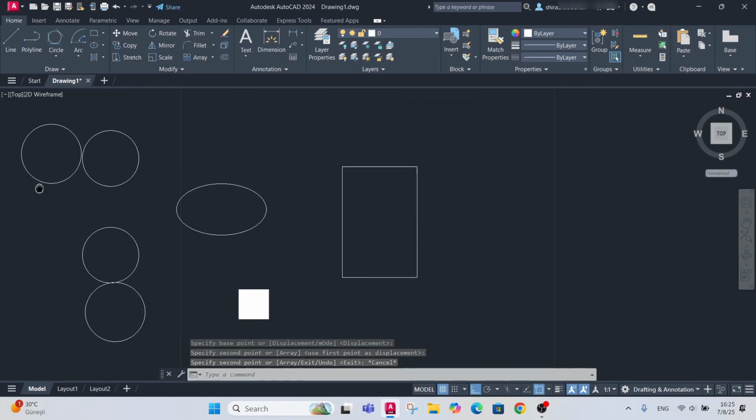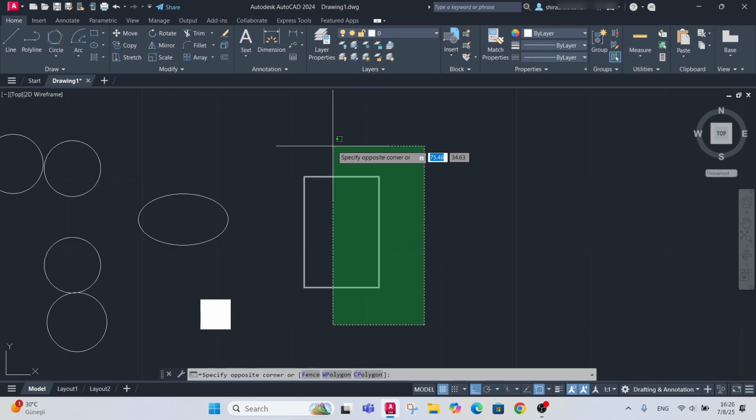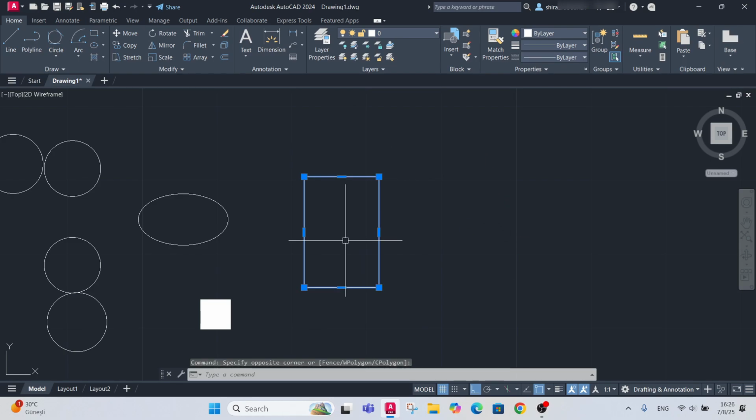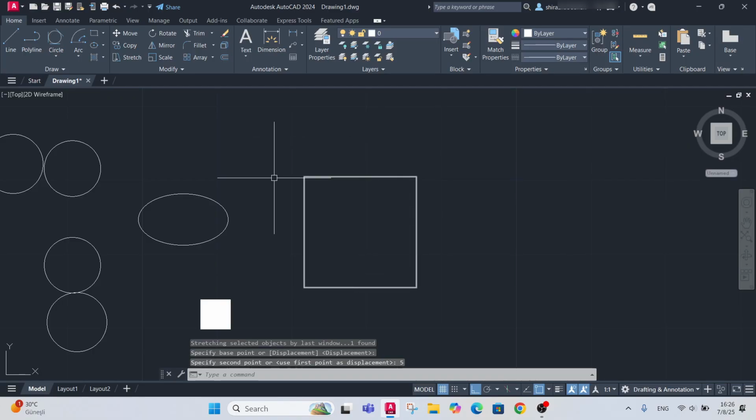Okay, stretch now. Maybe this was 10 and 15. I want to make it 15 by 15, and I don't want to start modeling it again. So maybe first select this side, the place I want to stretch, and then I know this one will be stretched and this one will not, because I didn't select it, and select stretch, and you see it's moved to this point, to this direction. See, because it was 10, I added 5. See, now it's 15 by 15.